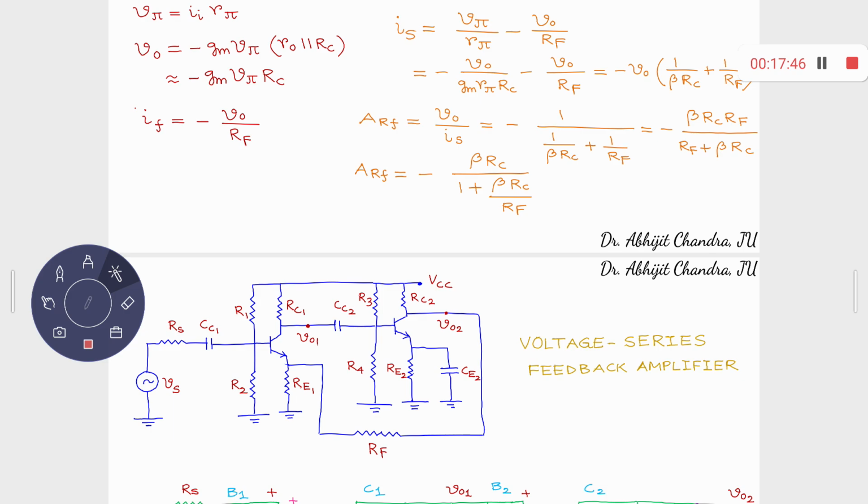Right? Then you understand that, okay, if my input variation is something like that, over here you can expect a phase reversal of 180 degrees, and then another phase reversal. Same phase. So if it is 1, 2 and 3, between 1 and 2 you have a 180 degree phase difference. Between 2 and 3, you have another 180 degree phase difference. So between 1 and 3, you have 0 degree phase difference.